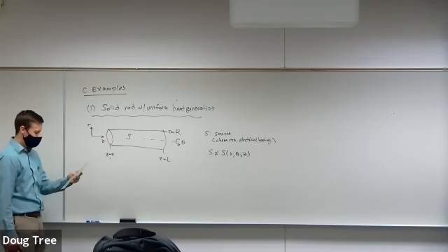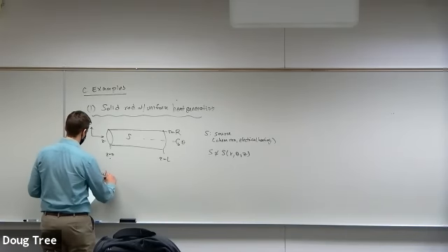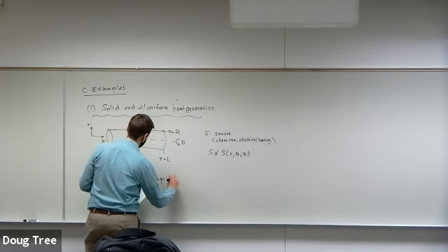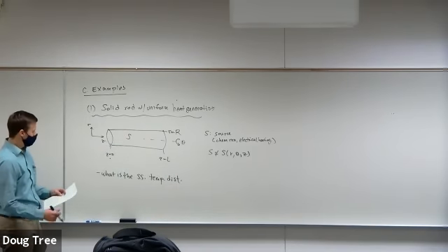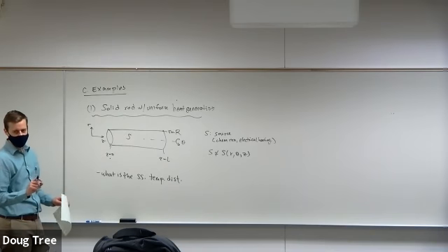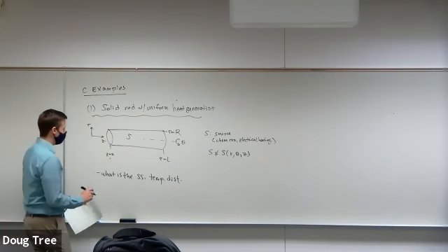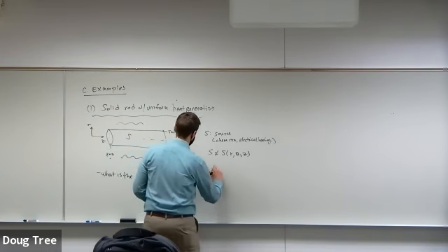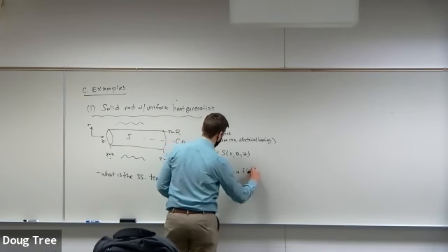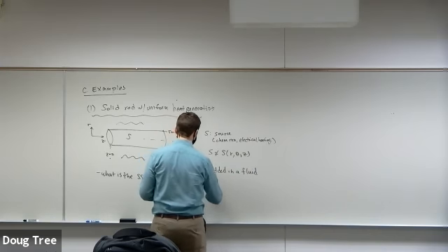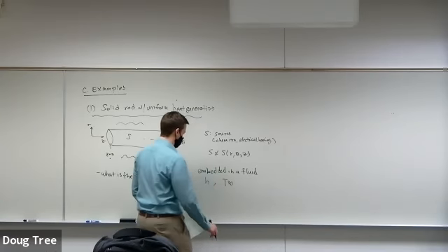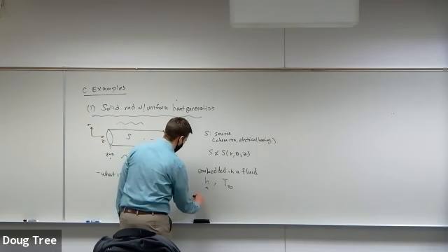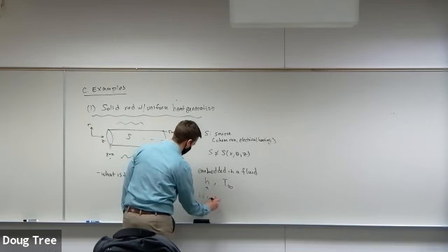So we're going to ask, what is the steady state temperature distribution? And we're going to assume that this rod, we'll make this a little more complicated than the simplest ones we would do from the shell balances. We're going to make this rod embedded in a fluid that has a heat transfer coefficient H and external temperature T infinity. Okay, so that'll be the heat transfer coefficient and an external temperature.